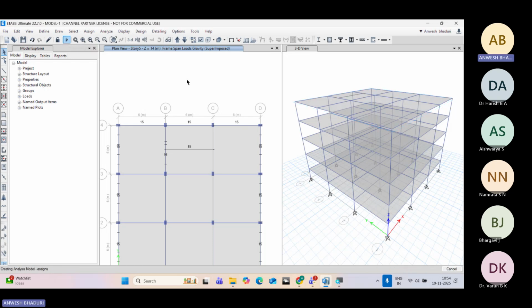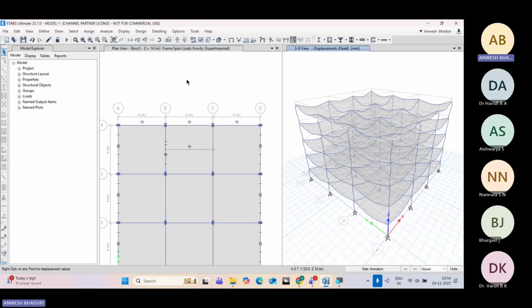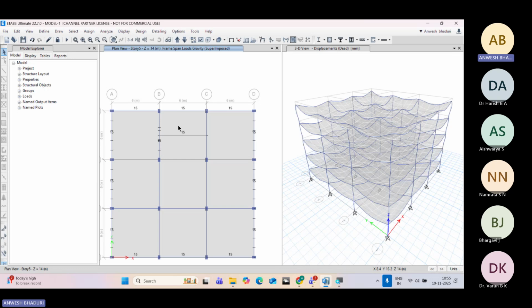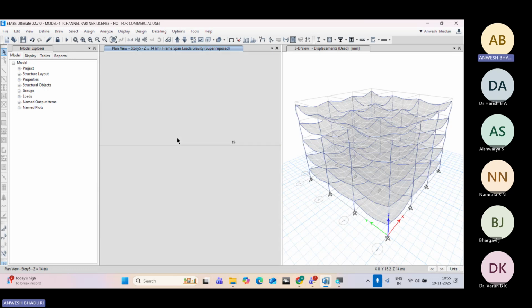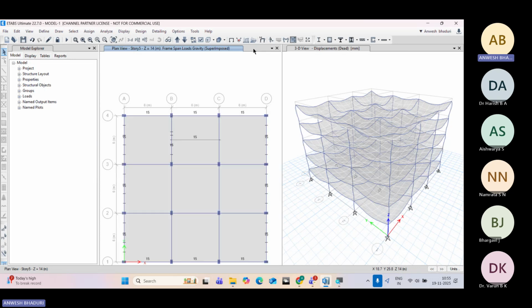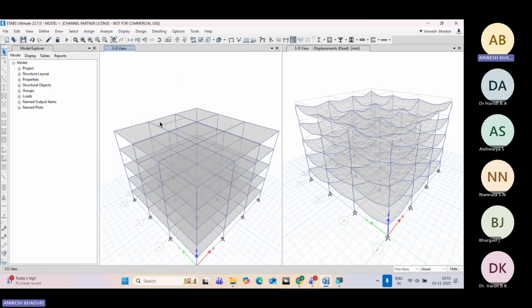So what happens is, when you're not having the out of plane stiffness, the bending in the slab will govern the load distribution. So you need to define this as a shell thin and draw a frame object of the property none, and then run the analysis.